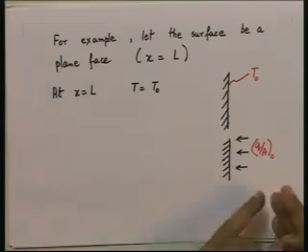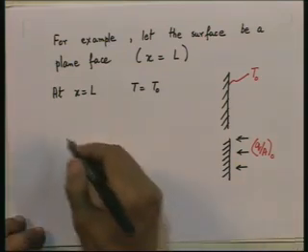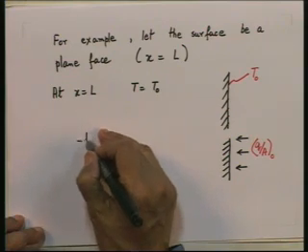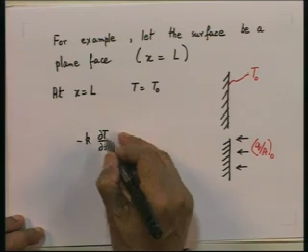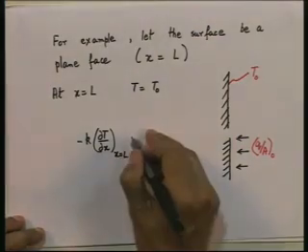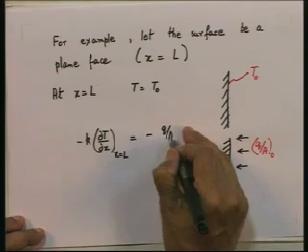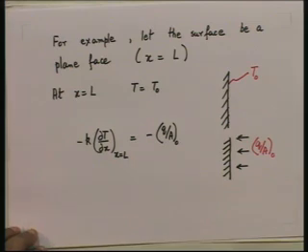So, we equate this flux to the heat flux we will get from Fourier's law of heat conduction at x equal to L, and the second type of condition, the prescribed heat flux, can be stated as minus K dT/dx at x equal to L is equal to minus Q by A naught. This is how the second type of condition would be specified.